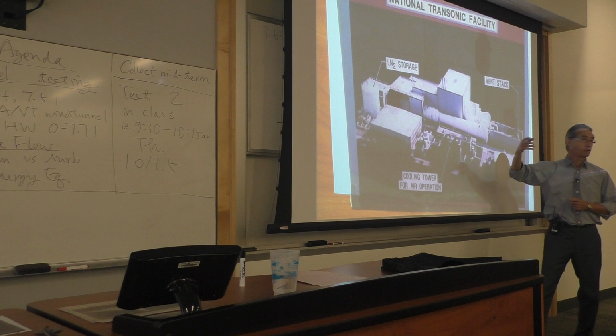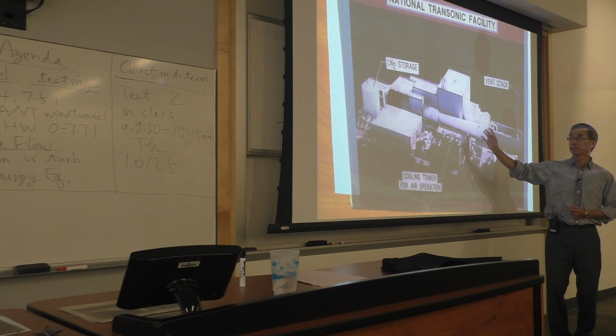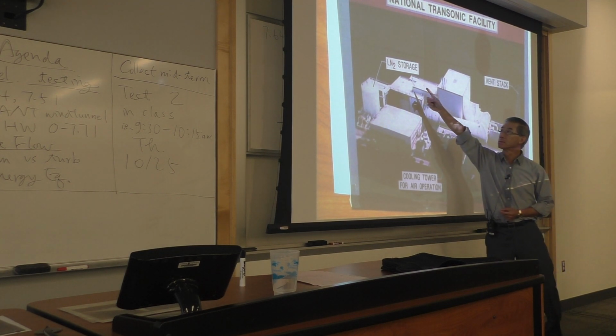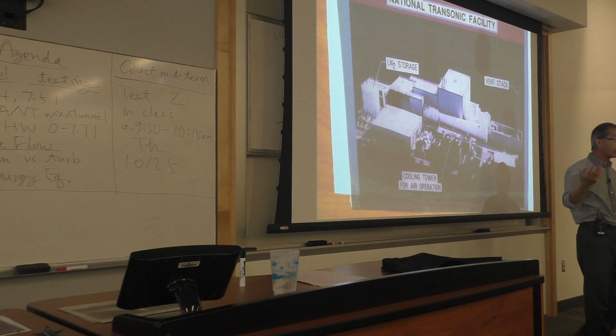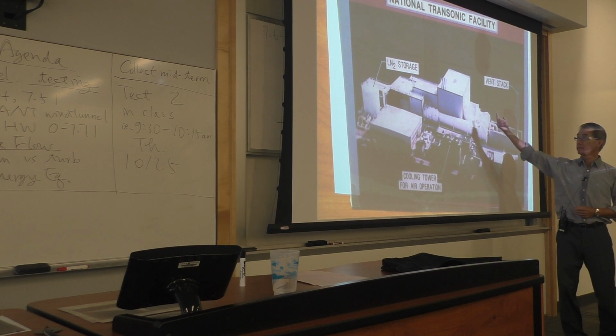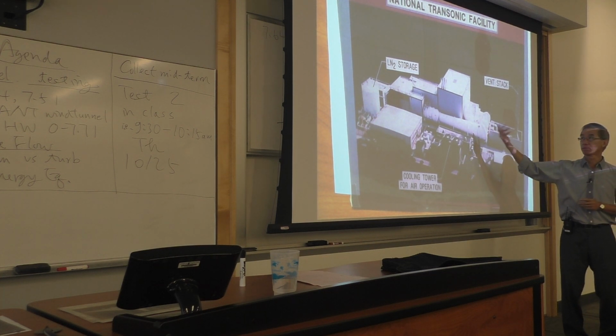By purging the flow of air before they start the tunnel, and all this takes a good part of half a day to a day, they purge all the air inside the wind tunnel, and then they circulate very cool nitrogen from a liquid tank, and they vaporize it to become gaseous nitrogen at cryogenic temperature, very cold, and then circulate that through the tunnel until they bring it down to minus 150 degrees centigrade, and then they do the experiment. In addition to that, they pressurize it.